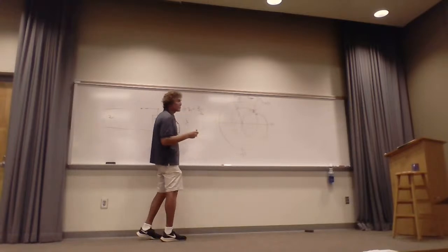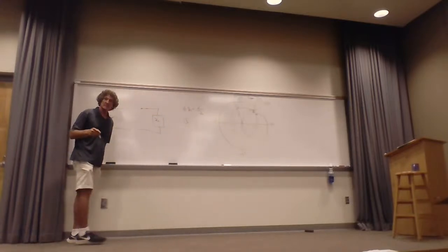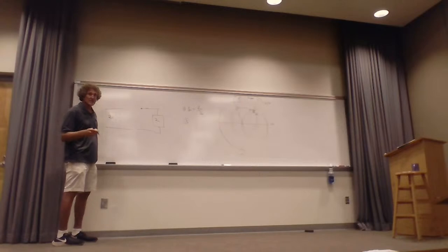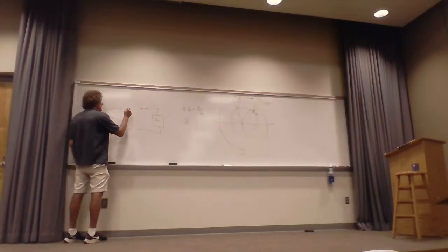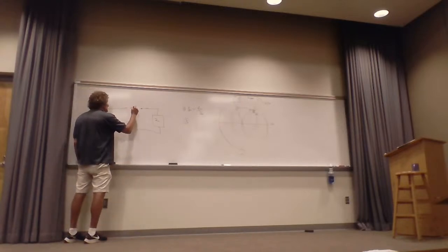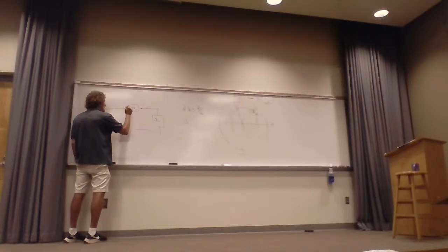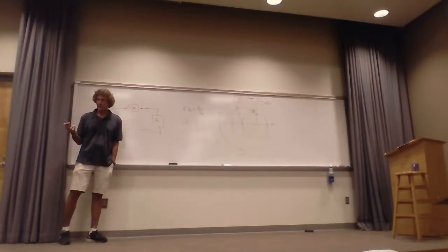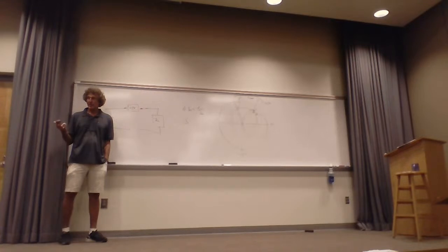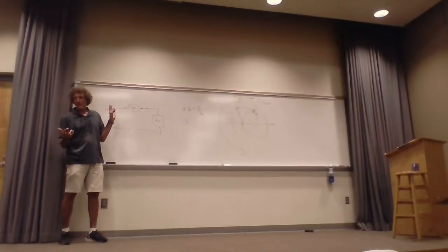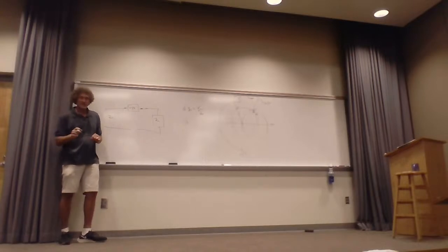Now, if I have 1 plus JX that's normalized, obviously you realize that I can do a couple of things. If I put in minus JX normalized here, then I'm impedance matched, correct? That's one way. And that's in series. If it was in parallel, I'd go to the admittance domain, and I'd find admittances that would do that, right? I'm just making sure everybody's clear about that.